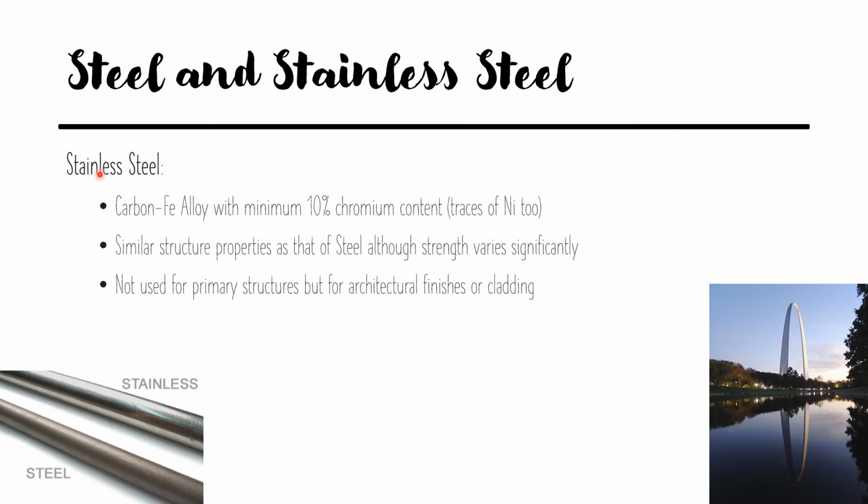In this slide, we will be talking about stainless steel. Stainless steel is one of a family of alloy steels that usually contains 10 to 30% chromium. I have mentioned minimum 10% here because it is the lowest level, but it can go up to 30% chromium composition. In conjunction with low carbon content, chromium imparts remarkable resistance to corrosion and heat. So this is a very important point: by addition of chromium we have heat resistance as well as corrosion resistance. And other elements such as nickel, molybdenum, titanium, aluminium, copper, nitrogen, phosphorus can also be added to increase the corrosion resistance to specific environmental conditions because it enhances oxidation resistance and also imparts special characteristics.